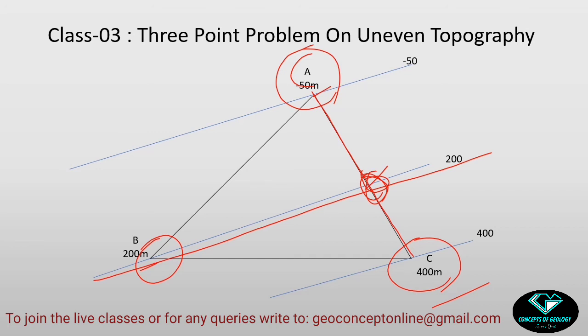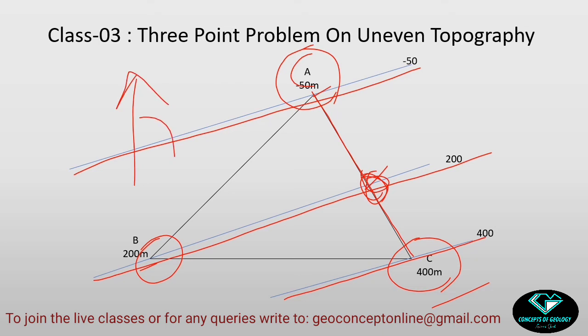Whenever I am getting this 200 meter stratum contour, I can draw the 400 meter stratum contour. This will move through this point C, and all the strike lines will be parallel. I can draw the minus 50 meter strike line also. This will move through point A, and it will also be parallel. So now we have got the orientation of the strike. We can measure the strike with respect to north also.